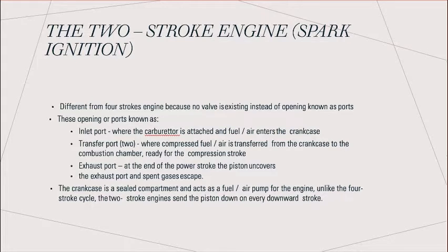The two-stroke engine performs all the same steps which are performed by four-stroke engines, like suction, compression, expansion, and exhaust. But the two-stroke engine performs all these steps in only two strokes, unlike the four-stroke engine, which completes one power cycle in four strokes. But two-stroke engines are slightly different from four-stroke engines because no valve exists; instead there are openings known as ports.